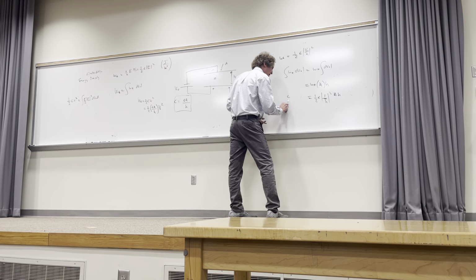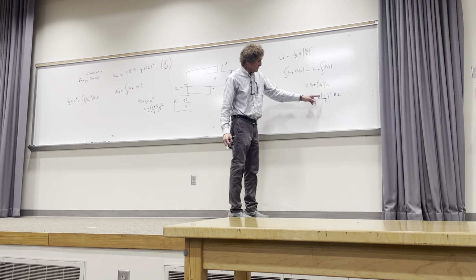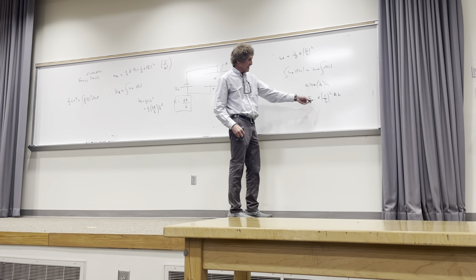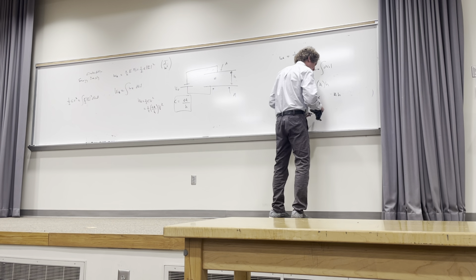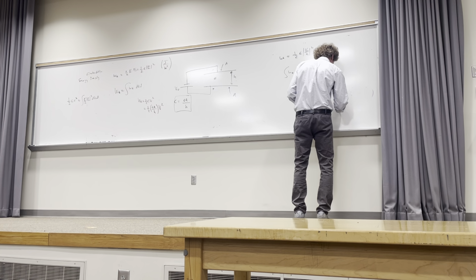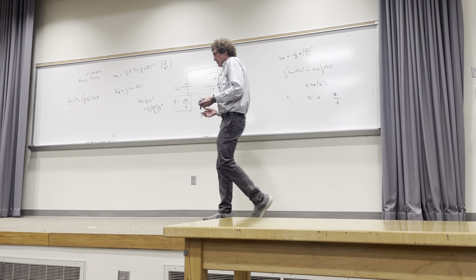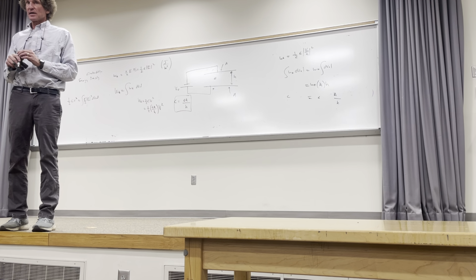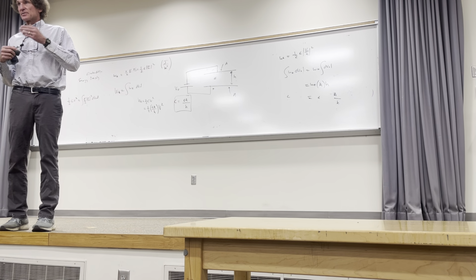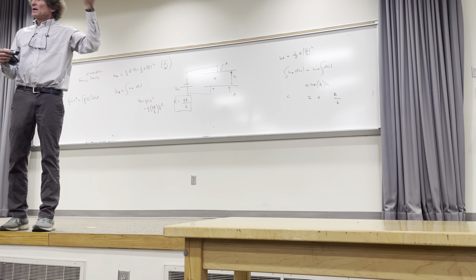Then I'm going to get rid of the 1/2, right? And, well, that 1 squared won't bother me, but I've got H squared downstairs and H upstairs, so it's really just 1 over H, right? And there it is, epsilon A over H is the capacitance as it was from our prior calculation. You can get it with either calculation, either energy density, or by doing assume Q, or in that case assume V, get E, from E, get D, from D, get rho S, from rho S, get Q, and going backwards.